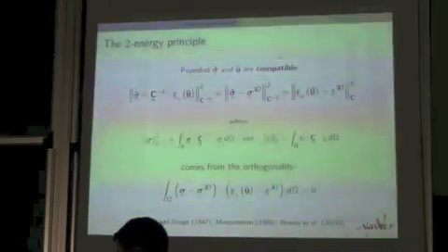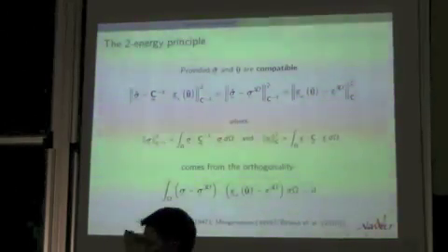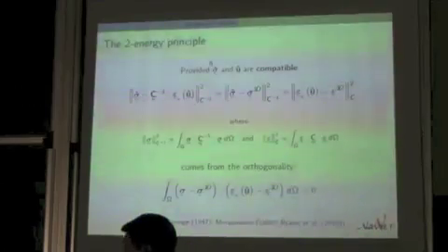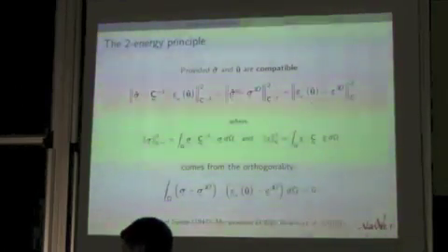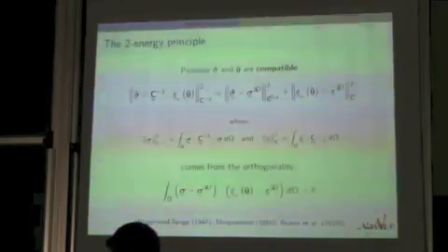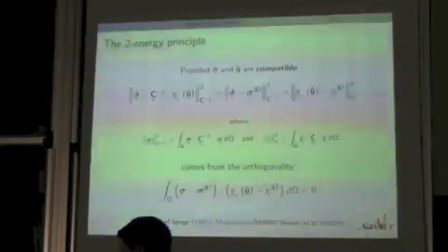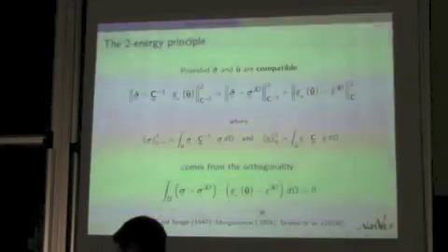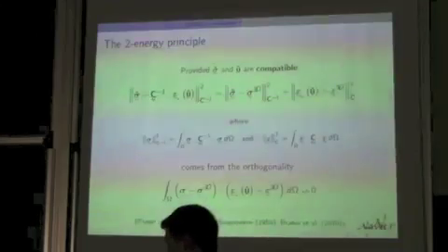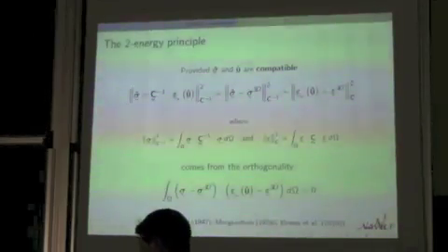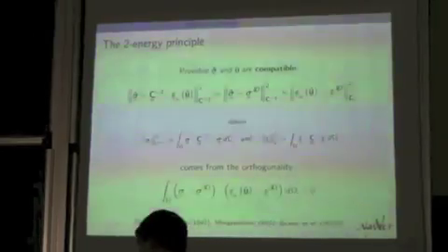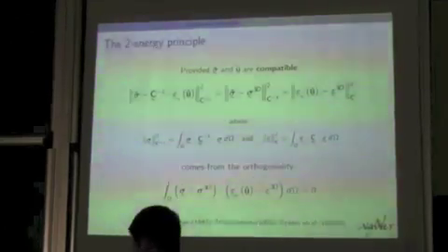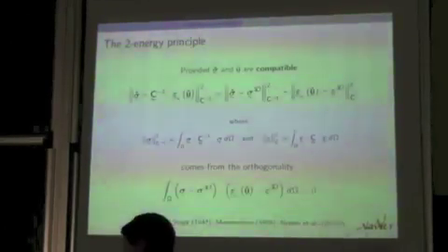So it's an estimate, okay, to have a range to estimate the distance between sigma and u, and it's exactly equal to the error with respect to the 3D solution. It just comes from the orthogonality relation, which is below, and which is quite well known. Okay, this is not new. This was used by Prager. It was defined by Prager and Synge, and used by Morgenstern and also Schwab, Bryce, and coworkers for plate theories, but homogeneous plates. Okay. So, I will use this principle.